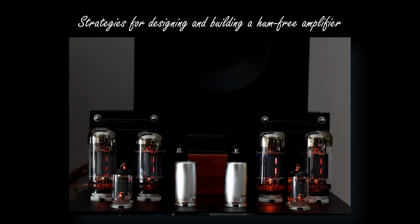You will remember we also spoke about the hum, which can be picked up mainly by preamplifier tubes, which are mounted outside the chassis, so they are exposed to the external world. Well, in order to get rid of this hum contribution, we suggest implementing tube shields, like the one you see now.